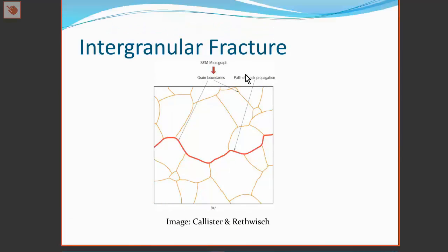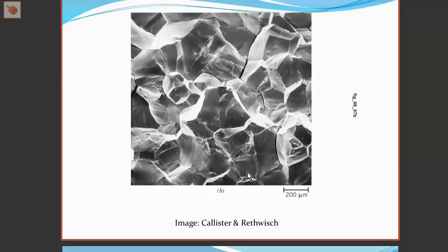An intergranular fracture is when the fracture propagates along or between the grains. This could occur if there is a second phase, a weaker phase, or a more brittle phase present at the grain boundaries, or another reason for weakening at the grain boundaries. In an intergranular fracture, the fracture surface is more faceted as it follows the contours of the grains.